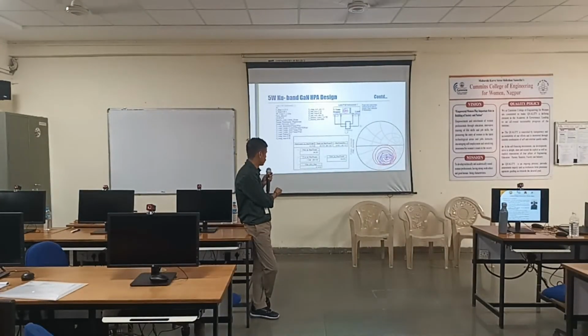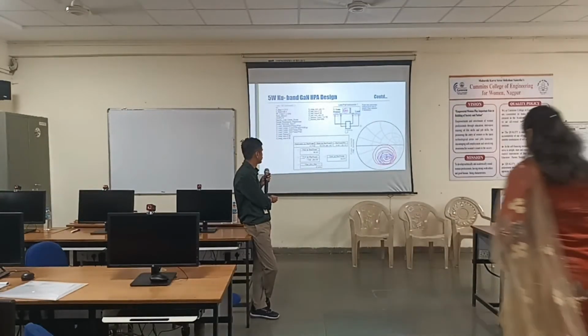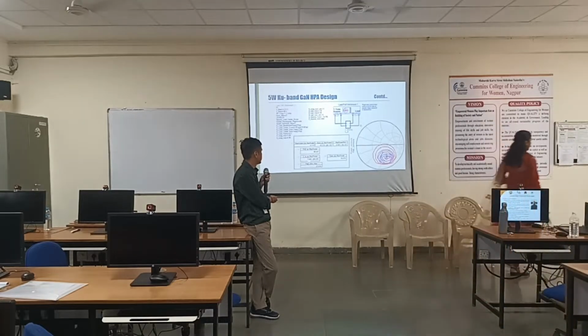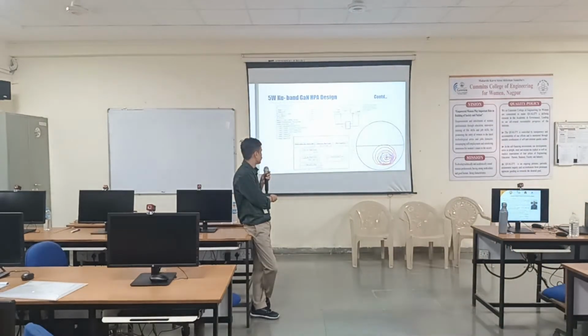So this is the step of load pull. From here you get the impedance. Can you see the number, complex number? So this you have to match with 50.